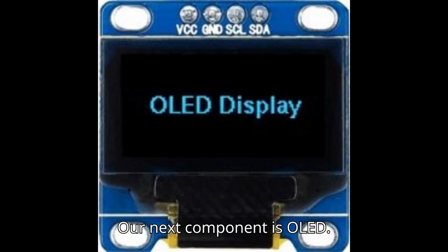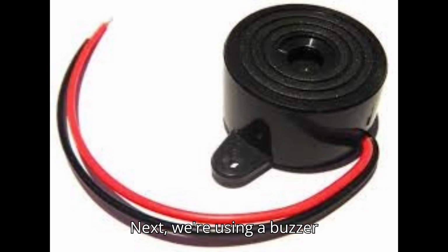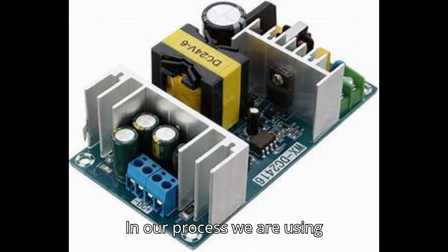Our next component is OLED. We use the OLED to display our results in the remote area. Next, we are using a buzzer to alert the farmer in the remote area. In our project, we are using 5-volt DC power. So this power converter helps us to convert 15-volt AC current to DC current.